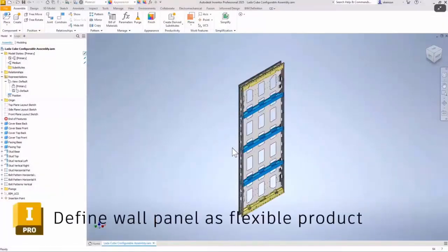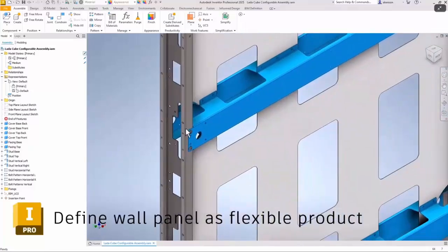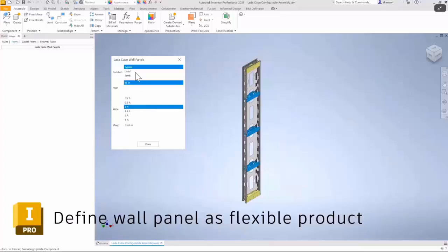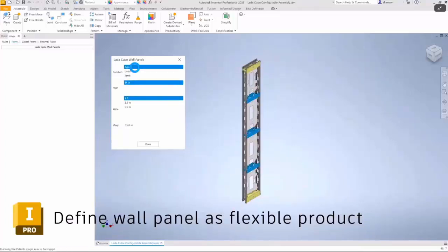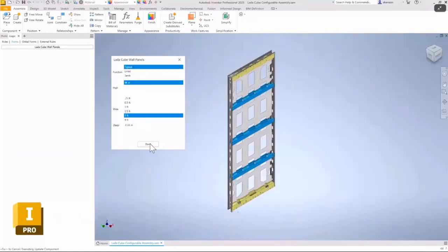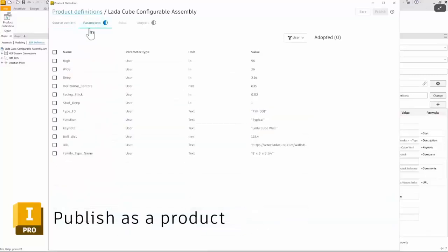What does this look like? We have a parametric component created in Inventor, something that would be drastically inefficient and hard to make in Revit. With all of these different versions, like I said, this only has to be created once, and all of these components can be transferred down to the Revit user. What we're doing is creating a parametric Revit family functionally through an Inventor product.